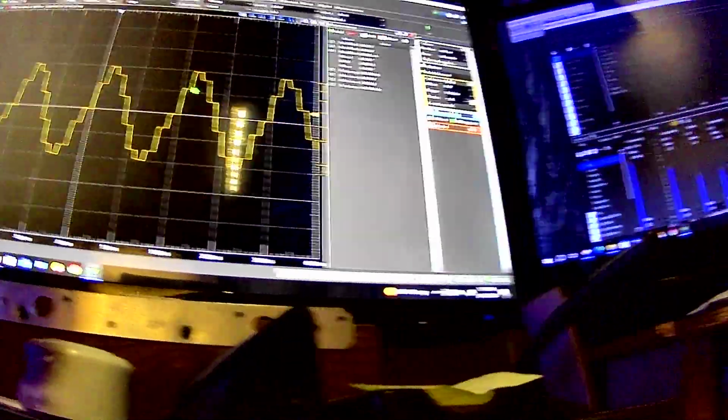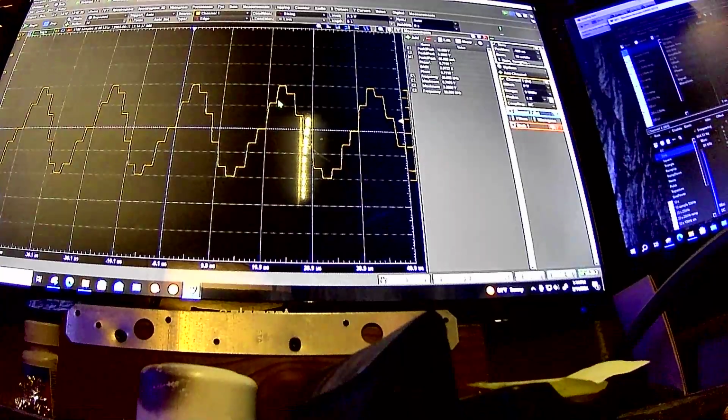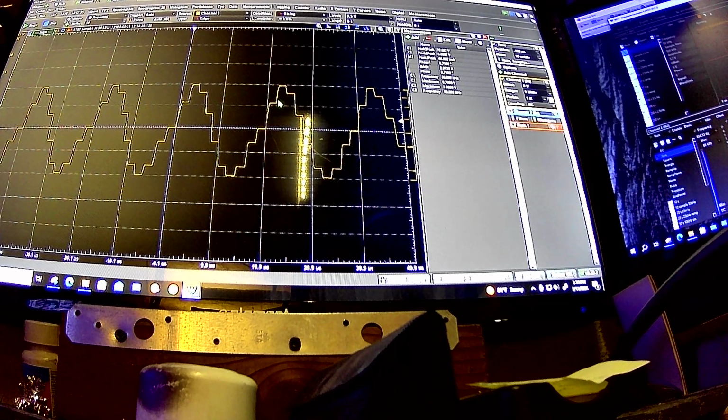So you really only get a few vertical samples altogether. That's your vertical resolution. Geez, even a 4-bit DAC would give you 16, right? So it pretty much sucks, but that's the best you can do for a 50 kilohertz signal. You can't do any better than something like this.